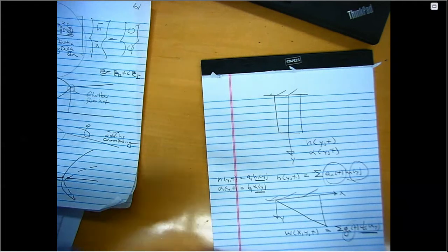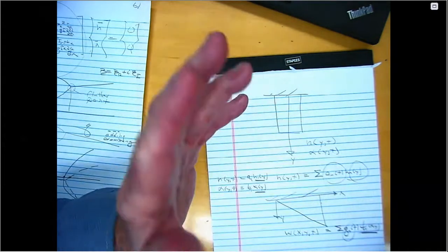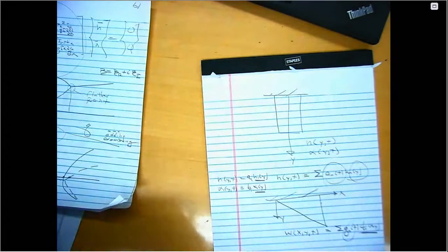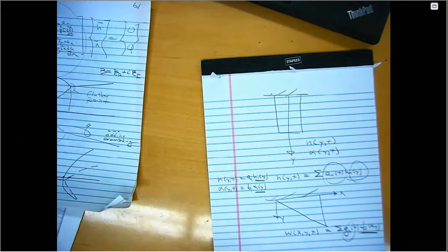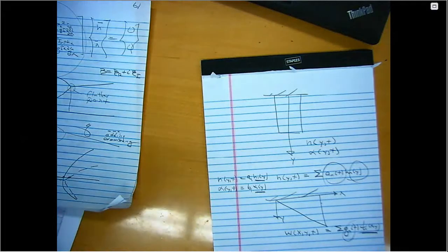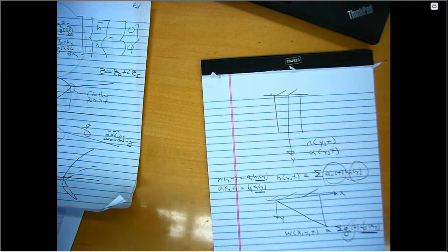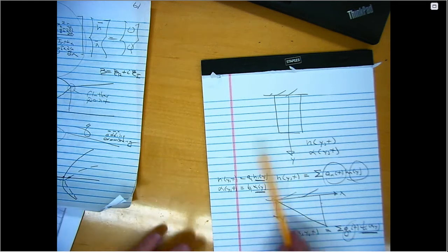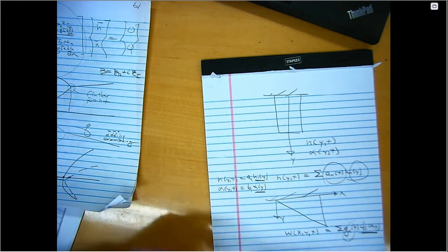But if I have to use 17 modes, or whatever the number is, I'm going to have a lot more equations. But qualitatively, I'll still be looking for two frequencies coming together. Now, it could be that it might be the fifth and sixth frequencies to come together. It doesn't have to be the first two. Often it is the first two, but there are well-known cases where it's not the first two. Okay. So, if you're going to do this model, it'd probably be good to use at least 3 or 4 torsion modes, just to be sure.